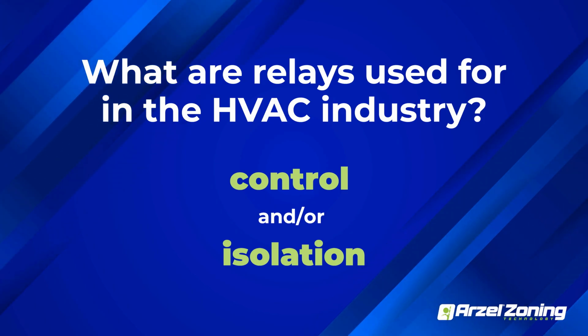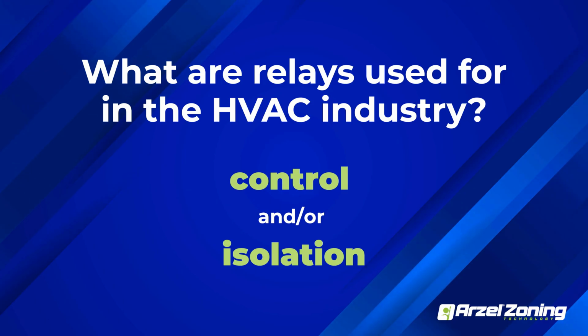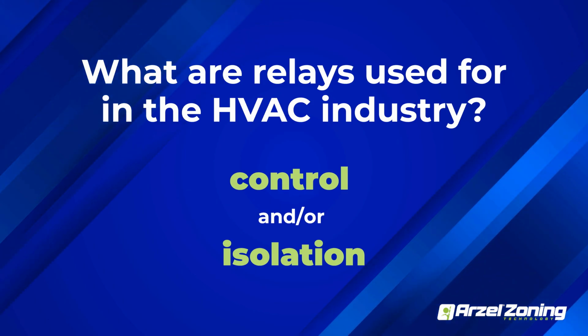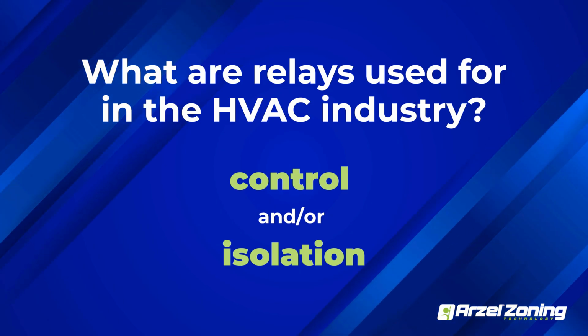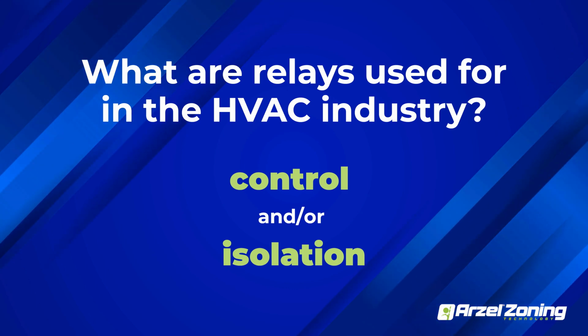So your HVAC outputs on the Arzel panel are dry contacts. We'll talk about that a little bit later, but that is your isolation. It separates out the transformer that powers the panel from the transformer that powers your furnace, because we need that additional power for the thermostats themselves.